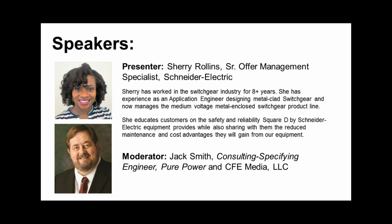It's going to depend on two things. Mainly, it's the number of operations you expect in the lifetime, and I think we mentioned that earlier. If you expect over 10,000 operations over the life of the breaker, one should consider withdrawable. It doesn't matter if you're fixed or withdrawable, the breaker technology is the same. If you're going to have 30 to 40,000 operations on the breaker, some generators are tripped very frequently, some are not. It's really going to depend on the application. So there's nothing about generators per se that would inhibit consideration of a fixed-mounted solution versus a withdrawable solution.